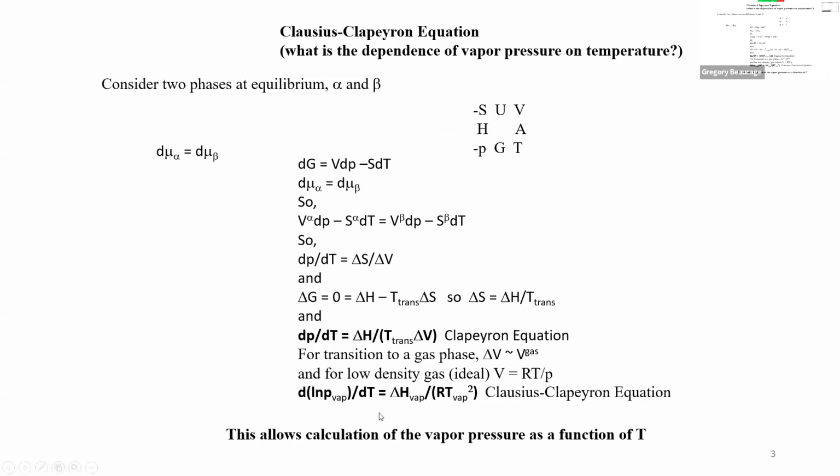And then Clausius did that for liquid to vapor transitions, like a chemical engineering transition. But materials don't really use liquid-vapor much, right? Unless you're doing vapor deposition or something. So anyway, if you're doing a vapor, then this thing no longer becomes a constant. It becomes dependent on temperature.